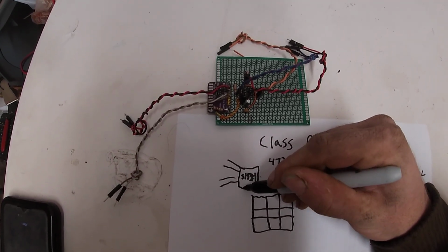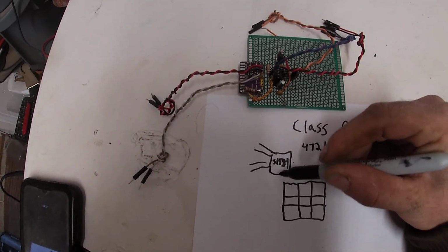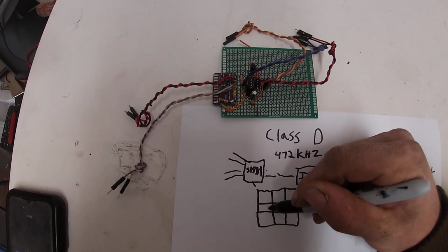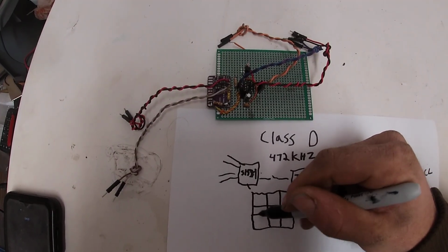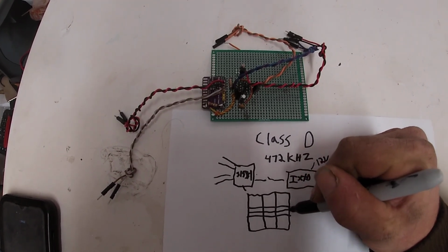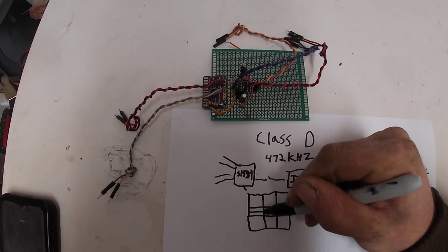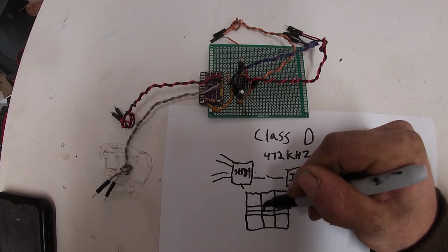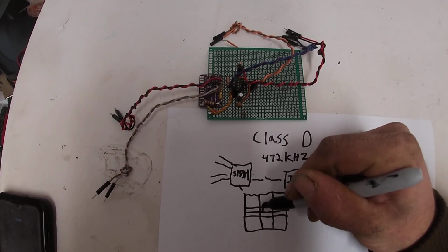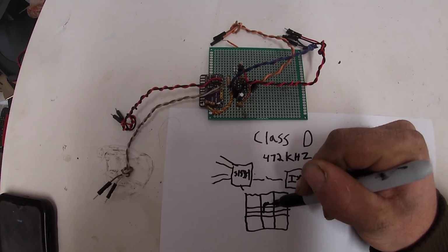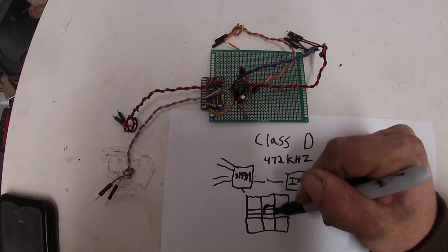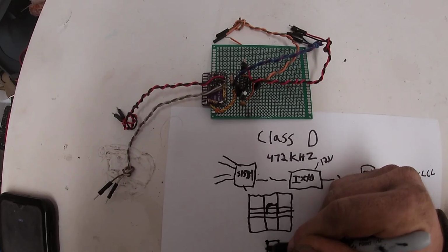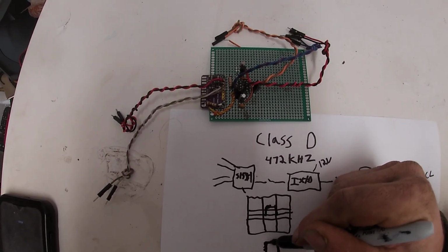If you tapped at this point right off of the SI 5351, you would have something to the effect of, well, we'll make that the 0 line. You would have voltage that ramps straight up, overshoots a little, maybe gets a little fuzzy, goes to a constant amplitude, and does the same thing when it turns off, like a square wave with fuzz all over it.